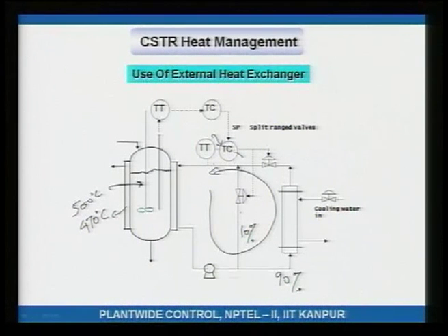Okay. So, let us say reactor temperature T reactor is increasing. If T reactor is increasing, I would like Tj to go down, so that more heat gets removed across the walls. For Tj to go down, you see this is hot, this is cold. So, the hot and the cold streams mix and they give you the Tj that you have here. So, if you want Tj to go down, you would like the amount of hot stream being sent here to reduce and the amount of cold stream to increase. So, to do that, what you do is reduce hot bypass.